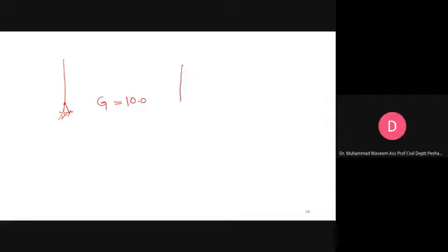And if we have this type of situation, we use a G value of 1, straight away. Now we already discussed that for a point connected to beams, you have to sum up the stiffnesses, moment of inertia divided by the length of the member.